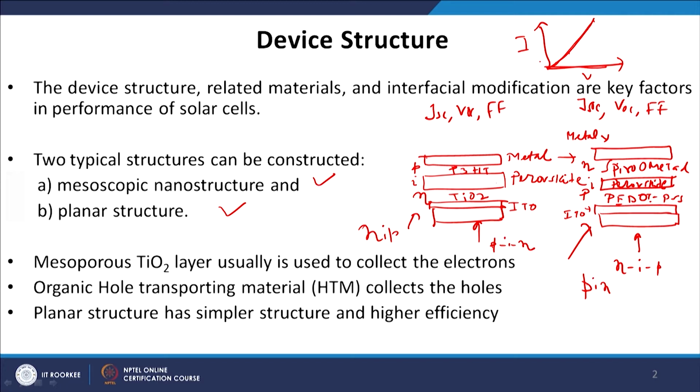But in the realistic case, it does not trace the same path, but it deviates from the path a little bit, and this deviation from the original path is called hysteresis, and this is an intrinsic property of the perovskite material. You remember when we discussed barium titanate or calcium titanate, and I said that in the earlier days the perovskite was mainly used for its good ferroelectric properties.